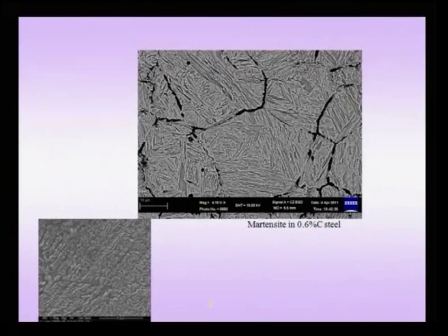So, we are now ready to summarize, and of course, let us start by seeing some typical Martensitic microstructures. Again you can see that in Martensite we have these kinds of acicular structures, and this is a typical Martensitic microstructure you would obtain. Needless to say, such a product is brittle and would need further heat treatments to make it an industrially important material. There are other microstructures of Martensite which are not that clear, but this structure seems reasonably clear when you see all these Martensitic sheets which are present.